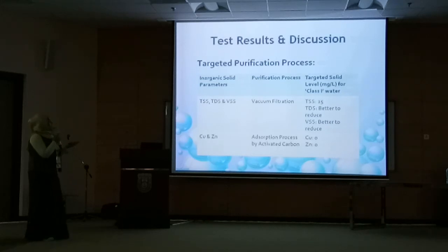Here is our targeted solid level. So we need these purification processes we haven't done, it's our suggestion. So we suggested vacuum filtration for lowering down TDS, TSS and VSS, and adsorption process for copper and zinc.